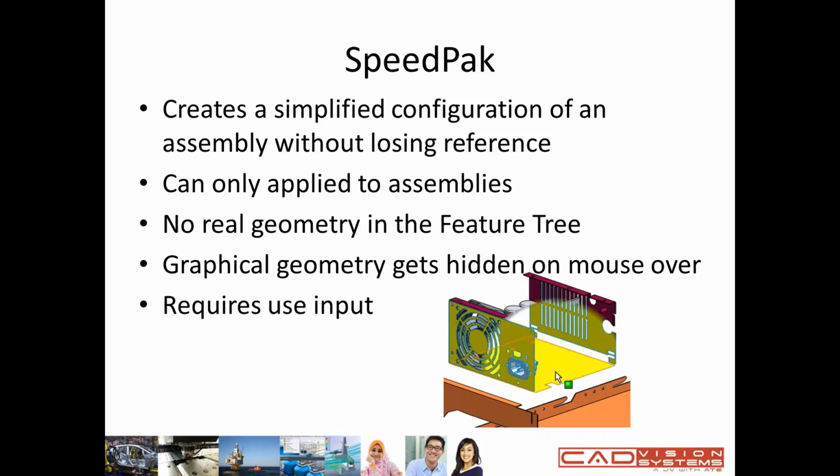So about the SpeedPak. Basically, SpeedPak creates a simplified configuration of an assembly without losing reference. It is only applied to assembly. There is also no real geometry in the feature tree, so graphic geometry gets hidden on mouse over. It also requires user input. SpeedPak information is only saved inside of the assembly.